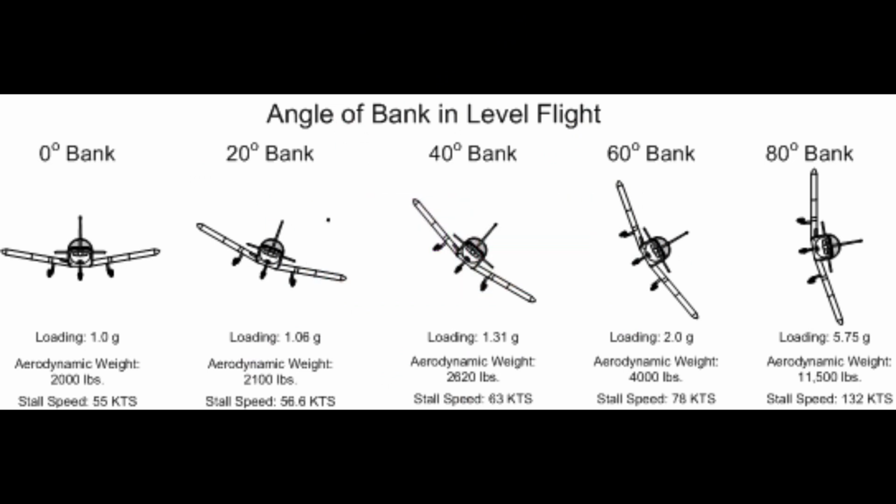Aircraft that do not have the category placard are designs that were constructed under earlier engineering requirements in which no operational restrictions were specifically given to the pilots. For aircraft of this type, up to weights of about 4,000 pounds, the required strength is comparable to present-day utility category aircraft, and the same types of operation are permissible. For aircraft of this type over 4,000 pounds, the load factors decrease with weight. These aircraft should be regarded as being comparable to the normal category aircraft designed under the category system, and they should be operated accordingly. Load factors in